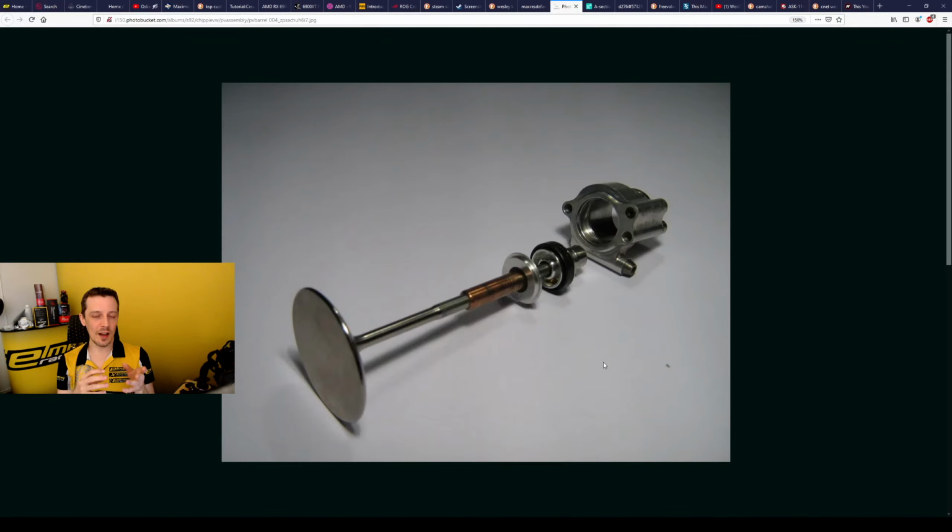And the exhaust valves, depending on the temperature, you might be able to run titanium. I'm not sure about the durability. You might be limited on the exhaust side and not be able to run titanium valves there. I'm not entirely sure. There might be some alloy of titanium that would work there for short durations like drag racing.